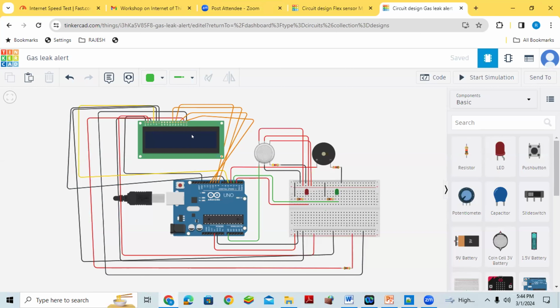Then this is a display screen, an LCD display, where we can display messages, whether it's an alert message or an evacuation message. Whatever message there is will be displayed on the screen. Now I have connected these devices to the Arduino controller. This cable is the 5-volt power, this is ground, and this one is resistors. If you don't connect the resistor, what happens? The full current will get into the device, and the device gets damaged. That's why we have resistors, to limit the current flow.